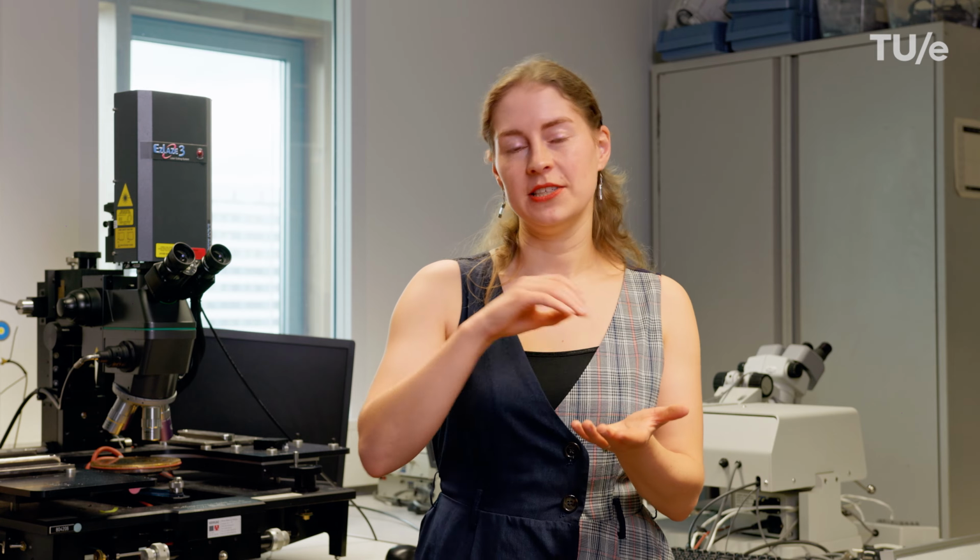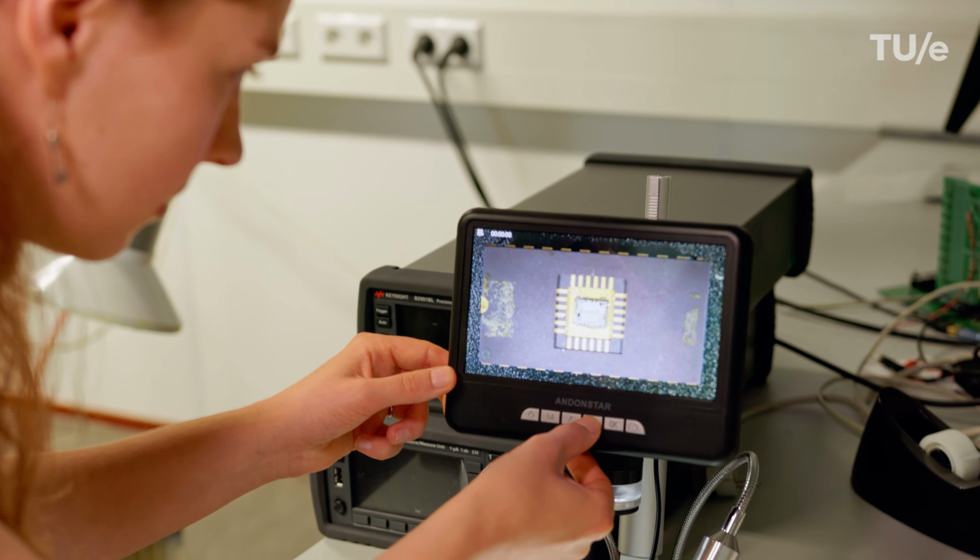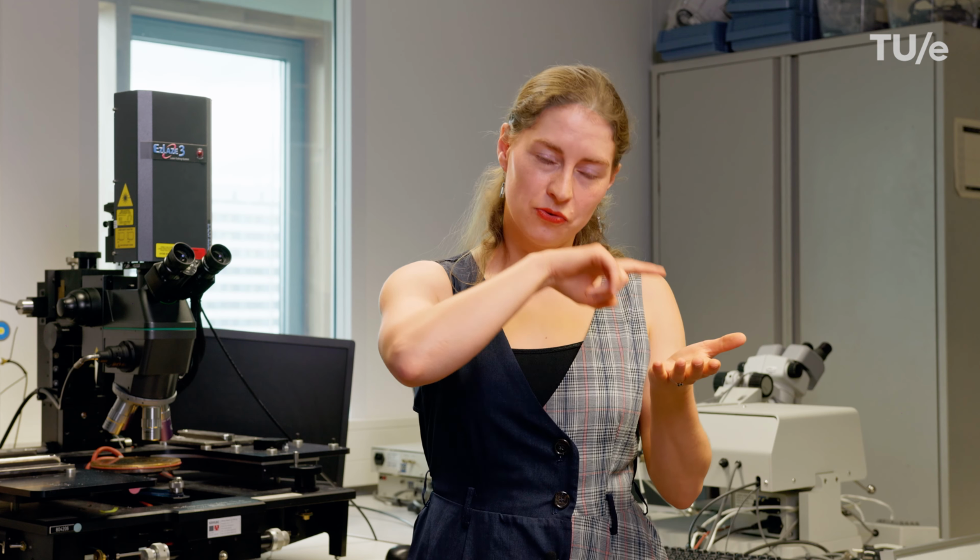Now, once your design is ready, you can create the actual chip layout. A computer chip consists of a lower layer of silicon. And in this silicon, transistors are embedded. Now, other layers of the chip consist of glass and metal. And through metal traces, you connect all the different parts of the chip with one another.